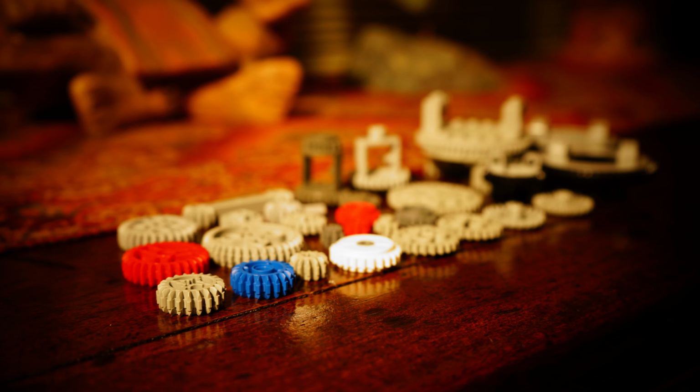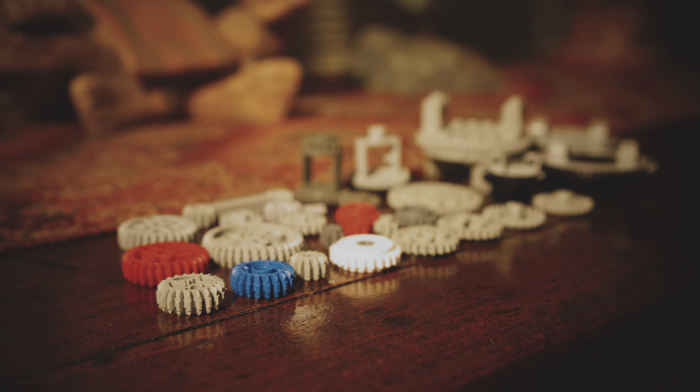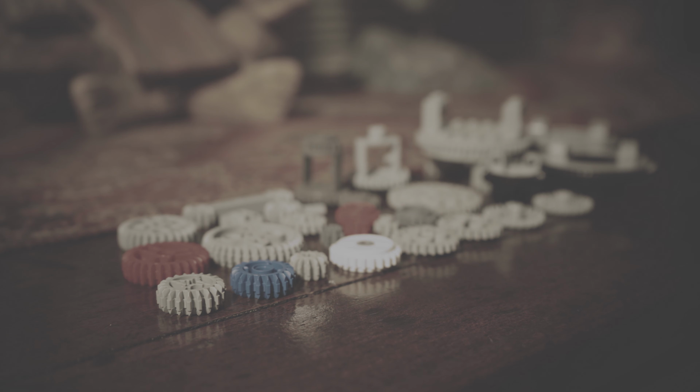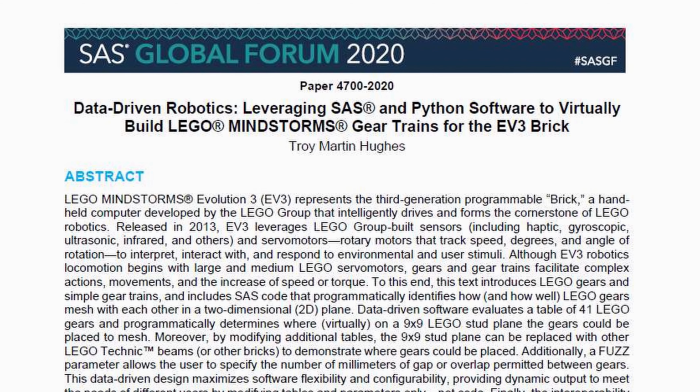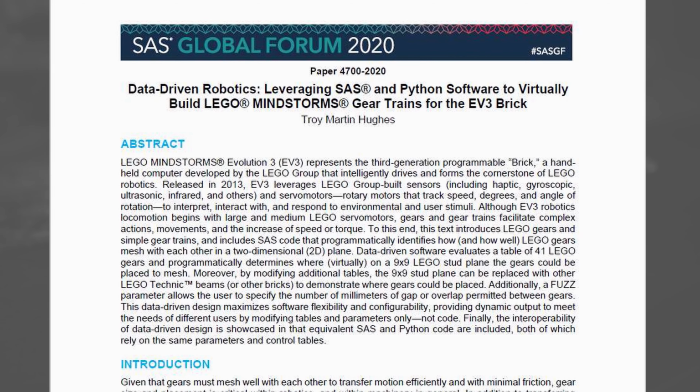Designing a simple gear train begins with a selection of gears that will mesh well with each other. Of course, simple gear trains can contain more than just two gears. However, each additional gear still represents only a one-to-one pairing between two neighboring gears. So for this reason, the gear trains examined will include only two gears. This video highlights only LEGO spur and double bevel gears.